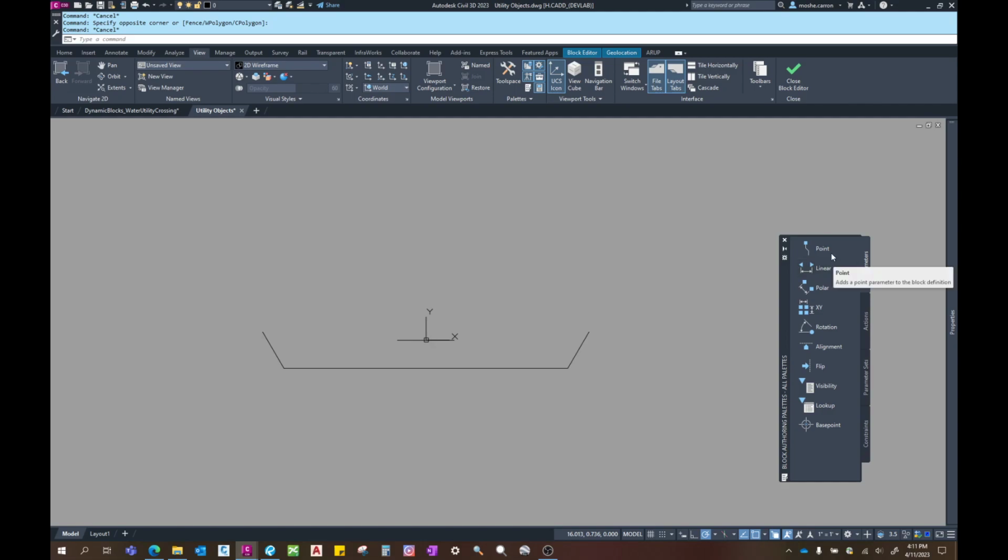Parameters define where the start and finish typically are, where the origin is, how to start creating an array, and how to move things polar or linearly or as a point, or flipping it. For example, if you wanted to mirror something, you could use a flip command.